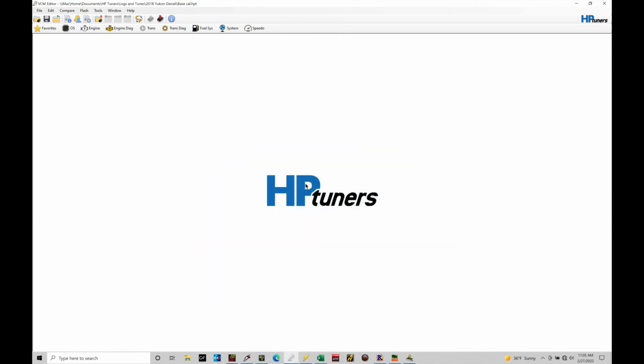Okay, so let's get started. We're going to be taking a look at working with our fuel injector programming in our Gen 5 applications. Now, the fuel injector programming is something that we want to understand so that we understand how the fuel mass is converted into an injector pulse width. It's going to be quite different in terms of the programming and the flow of how the injector data is going to fit into that conversion compared to the Gen 3, Gen 4 applications where it was a port injection engine. The injectors are actually mounted in the intake manifold and they spray above the intake valve.